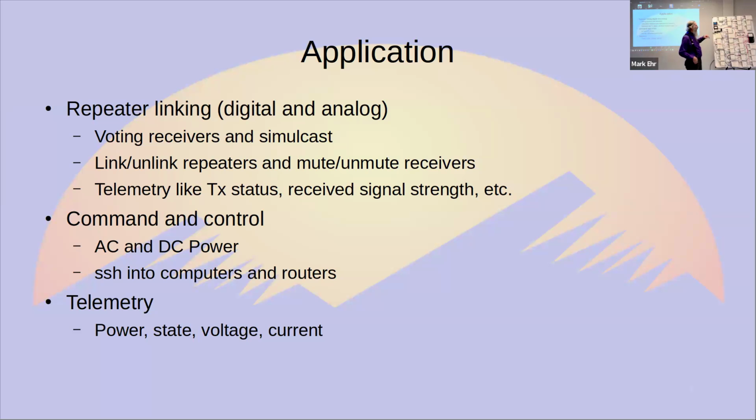What this represents with all of these purple wires are actually microwave links. All of these purple wires you see all over the board represent something that typically has one of these on one side or the other. This is just a 2-foot high gain antenna. This one is particularly for 5 gigahertz, and it's a 30-something dB gain antenna.